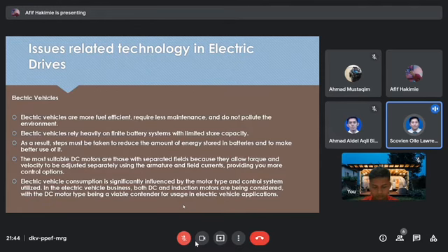An excellent carbon brush can help you figure out which brush grade is suitable for each of your applications in order to deliver the complete current density at the point of contact and minimize early brush wear. It is also necessary to maintain correct, consistent pressure on the brush of the commutator. Next.